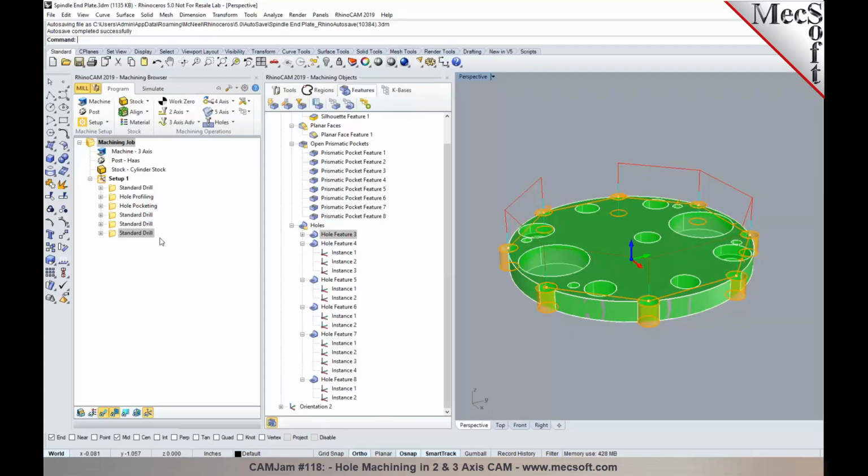So you can program each of these hole features, and one of the nice things you can do is save the hole features into a knowledge base. If you have other parts that have similar cross sections for through holes or for counterbore, you can program them, and I'll cover that in another example.